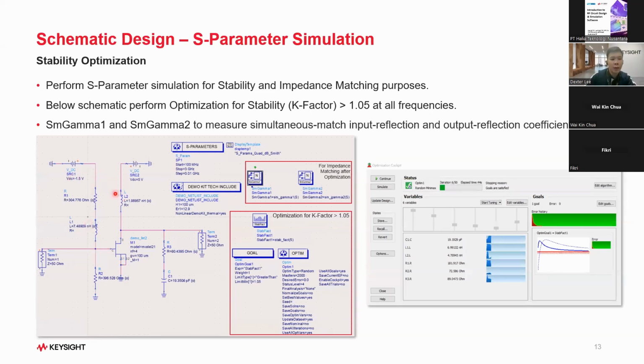This is a network that I created, with a rough idea that my stability network will consist of resistors and a few inductors here. And towards the load, it is connected with a resistor and capacitors. This is really just an initial stage of creating a stability circuit. Once I've placed my lumped components here and connected them with my transistors, these are also the VDS and VGS biasing values that I determined earlier for my DC FET.